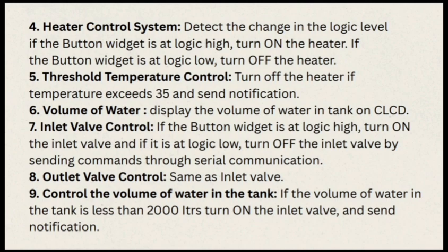Seventh one is inlet valve control. The inlet valve is operated using a button in the GUI. In the simulation, if the logic is high, then it opens the valve. If the logic is low, then it closes the valve. Commands are sent via virtual serial communication.